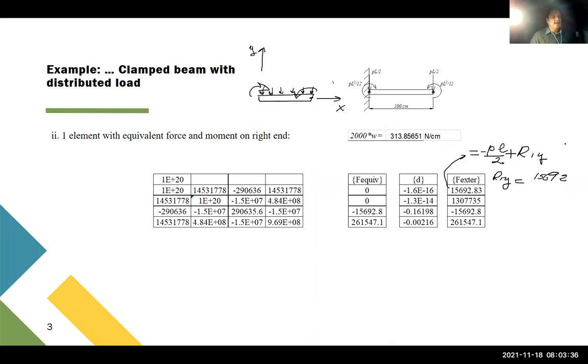And then we put this on the other side, so it's going to be plus. And this value is equal to this one. So it's going to be 692.8 or something like that. So that is going to be the reaction. So we're going to have at the end, this force here, and the reaction here. So the reaction will take care of this plus that. Makes sense. So you can do something similar for that in order to have the moment reaction in here.